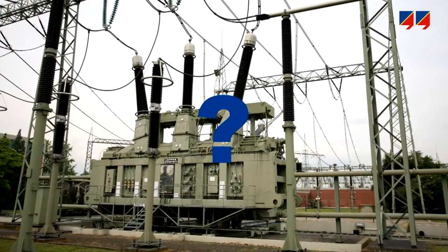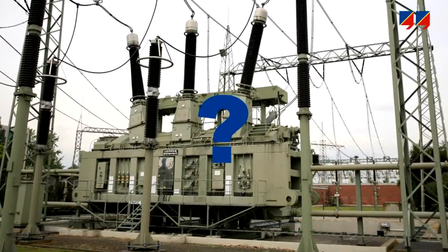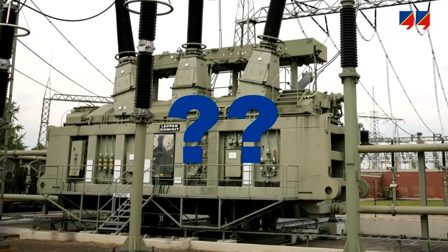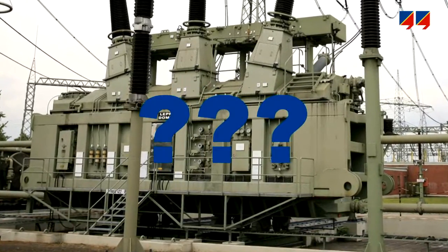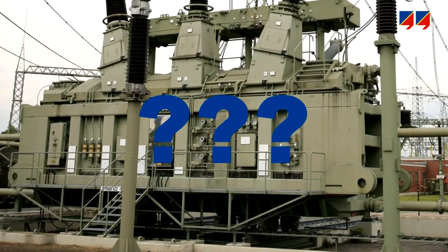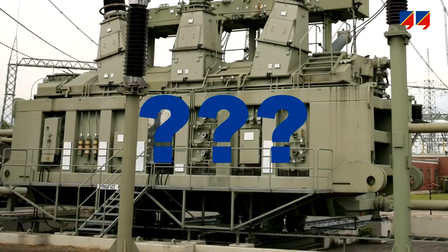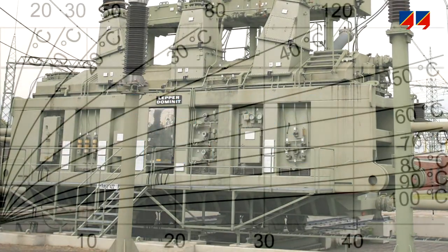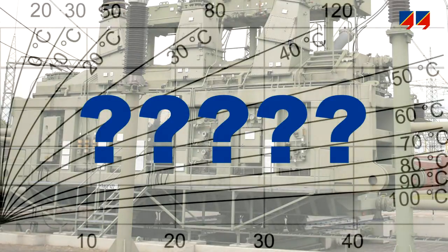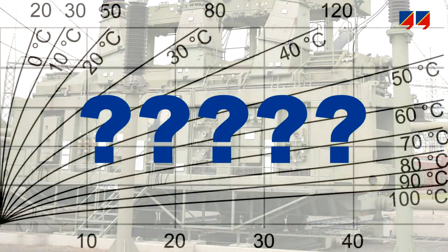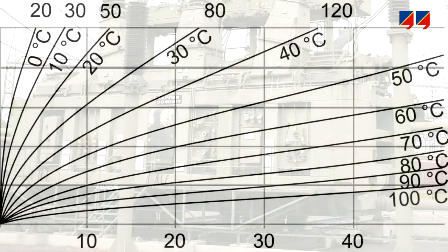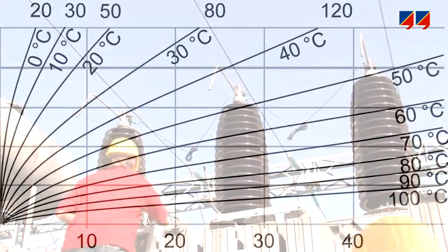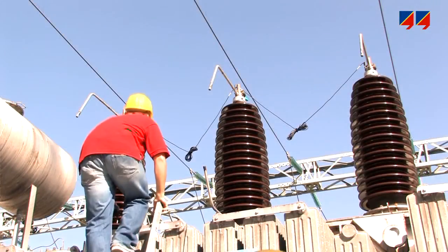How does the transportation of the sample to the laboratory influence the final result? Is the titration method also valid for an aged transformer? What influence do dynamic temperature and load changes have on equilibrium? Are the equilibrium curves valid for all types of oil? And are the curves accurate enough to give a realistic result? These uncertainties, plus the roundabout way of approximating the moisture in paper via the moisture in oil, call for a more direct and precise method.